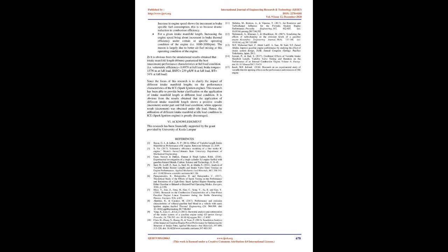While, for 60 mm intake manifold length with the same technical operation parameters under consideration, BTE are 32.45% and 32.69% respectively. Also, no significant change in BTE was obtained at this operating condition of the engine, just as it was obtained under 50 mm intake manifold length. Thus, from the foregoing analyses it can be concluded that no significant change in BTE between these two intake manifold lengths under consideration was observed.